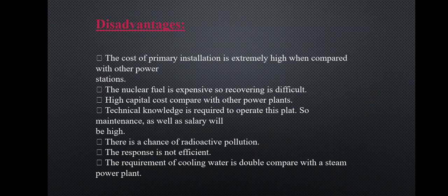Let's see the disadvantages. The cost of primary installation is extremely high when compared with other power stations. The nuclear fuel is expensive, so recovery is difficult. High capital cost compared with other power plants. Technical knowledge is required to operate this plant, so maintenance as well as salary will be high. There is a chance of radioactive pollution. The response to load changes is not efficient. The requirement of cooling water is double compared with the steam power plant.